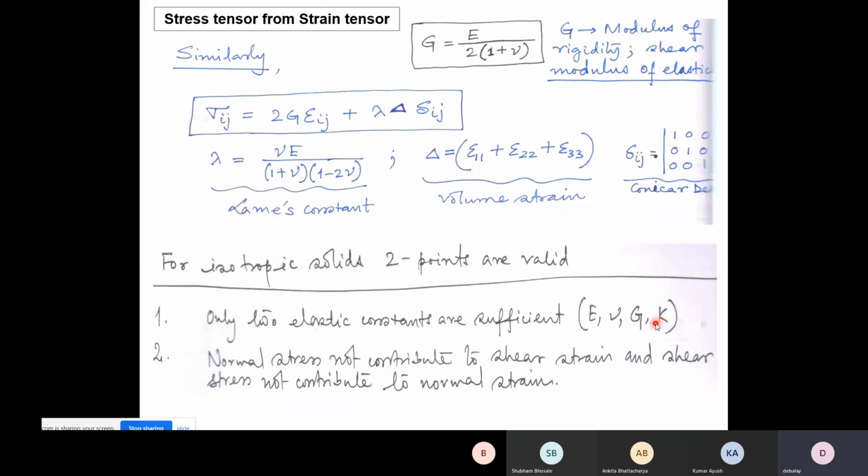At the beginning of the course, we used certain words: continuous, homogeneous, and isotropic. So all these expressions are applicable to isotropic conditions. We have one assumption that we are using an isotropic body, but the property is the same and the elastic constants are the same along all the directions. But whenever we see a real crystal, starting from cubic to triclinic, the degree of anisotropy increases.